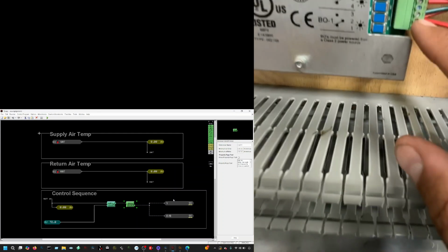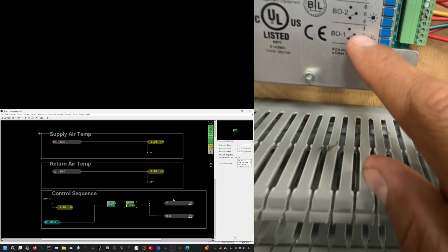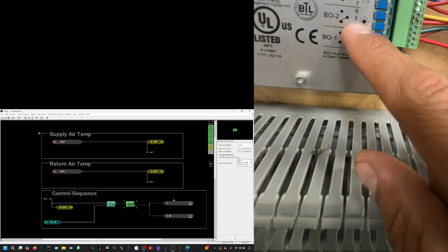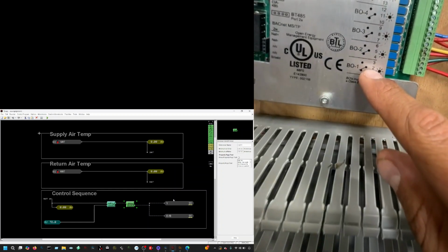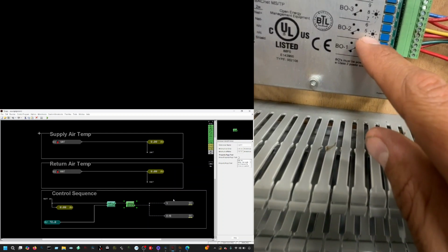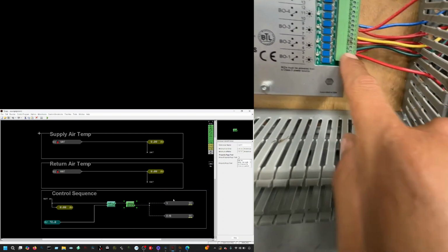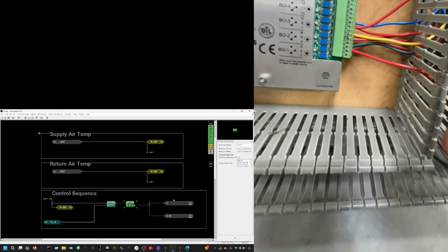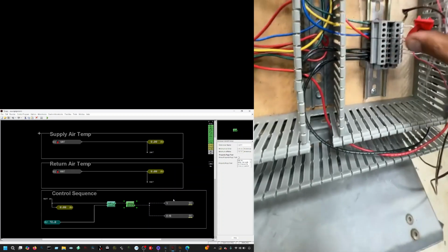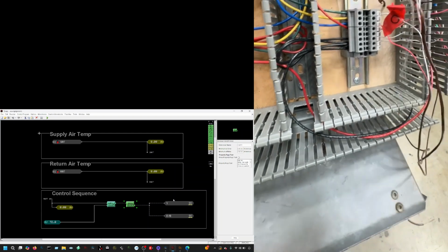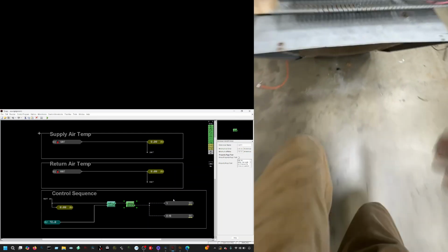my power from right here, binary output 1 from 2, and binary output 2, number 5, they're going to go like this. Boom. So 2 is going to give 3 24 volts, and 5 is going to give 6 24 volts. And whatever wires I have coming out, that's going to receive 24 volts. And these wires, I have a green and yellow that essentially end up being my Y and my OB, because we already followed the 2 wires coming out.